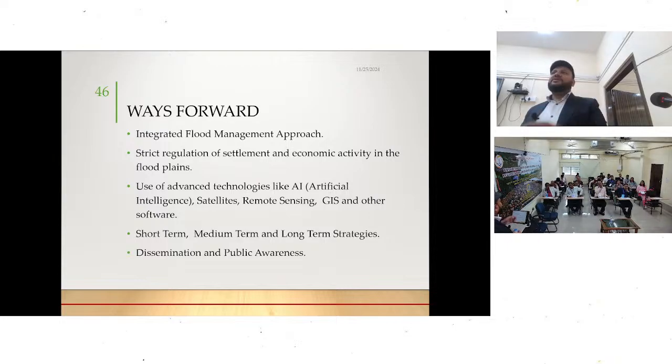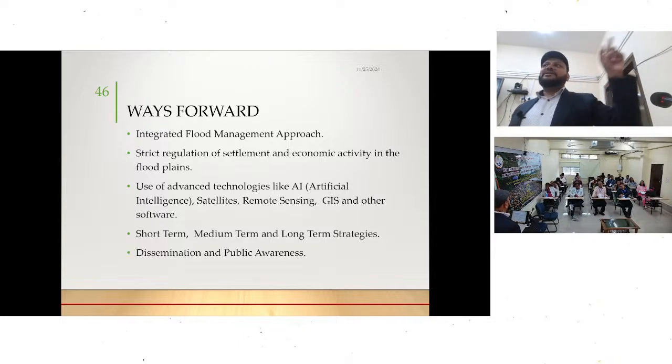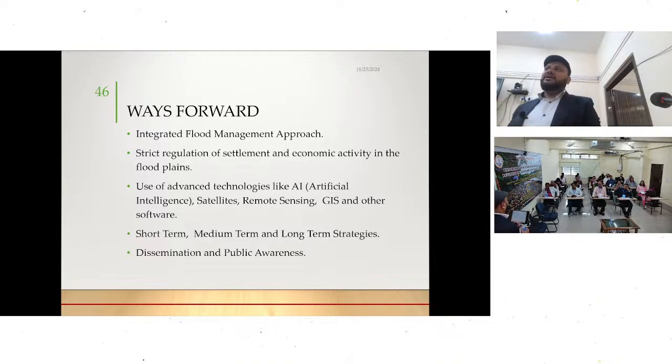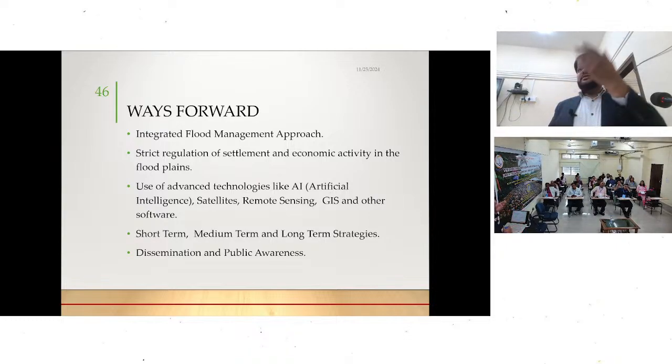The same thing happened when I was at the Ganga Flood Control Commission in Patna. Nepal constructed RCC bank revetment in their area at Dharchula, in Pithoragarh district, Uttarakhand, where the river is the boundary. Due to those measures, the river was diverted into India, started eroding the Indian part and changing the international boundary.